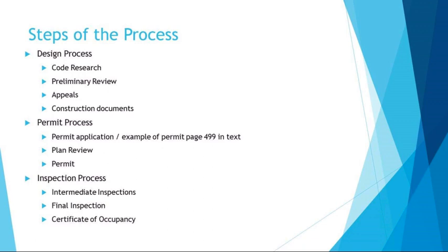If a design requires the use of performance codes instead of certain prescriptive requirements, remember we learned the difference between performance and prescriptive, then a preliminary review with the code official is necessary rather than optional. In fact, a concept report has to be submitted before beginning the design.